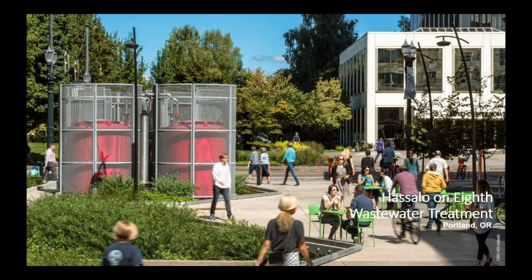In terms of quality at the municipal scale, let me kind of work backwards, and Aaron, please help me remember the questions as I go through them. But municipal scale, that's a little bit of a misnomer, that it's better at municipal scale in terms of recycled water. The opposite is true in a lot of our West Coast communities. For a long time, folks in the Bay Area did not want to use reuse water because of the amount of salt that was in the collection and distribution system for that water, and so it was fairly salty, and people didn't want to tie into the municipal system, but were excited about a smaller decentralized system, maybe at the building or neighborhood scale.